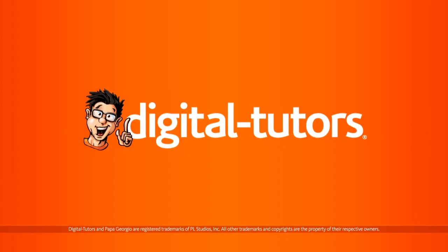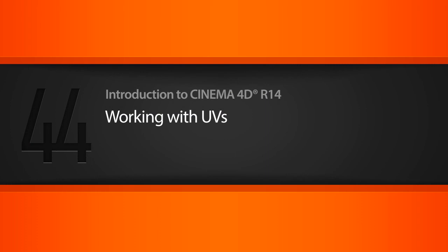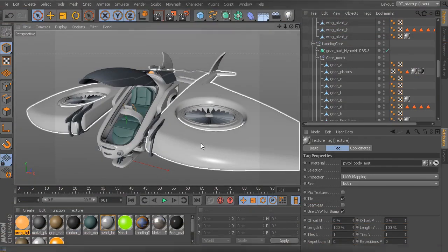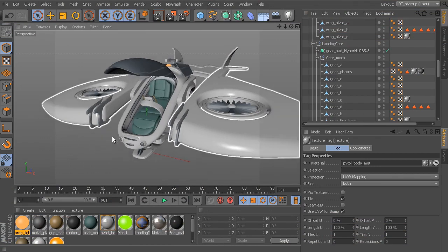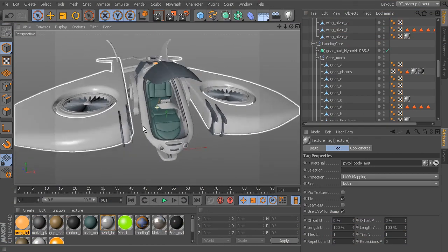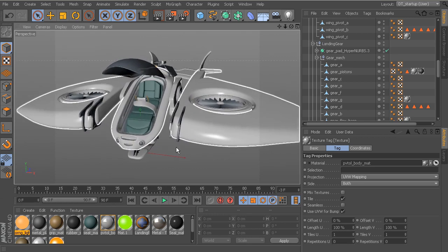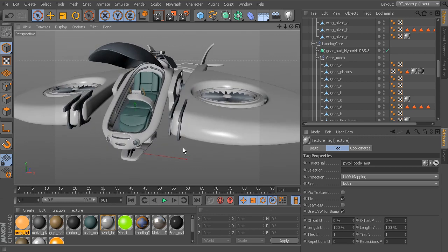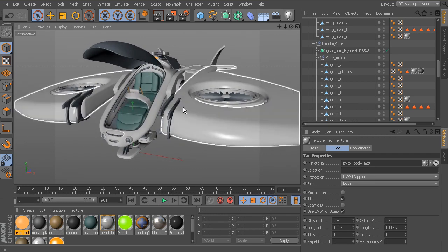In this lesson, we'll talk a little bit about UVs and creating UV layouts for some of our pieces. Up to now, we've been just adding simple materials and everything has been fine. The material attributes, you can see the different material types here, but when you start to get into adding texture maps or other kinds of images to your polygons, you want to define how the polygons are going to be able to show those textures, or how they receive the textures. And to do that, we need to set up some UVs in many cases.